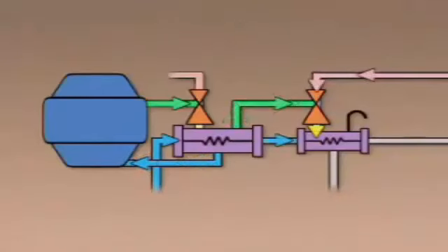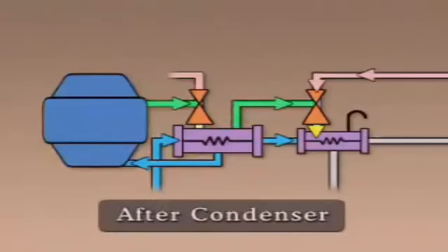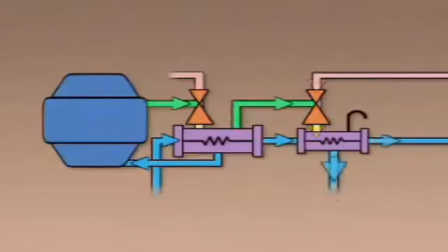The steam-air mixture that leaves the second-stage ejector flows into the shell of a second condenser called an after condenser. There, the steam is again condensed and routed to a drain tank or back to the main condenser. The air is vented to the atmosphere.